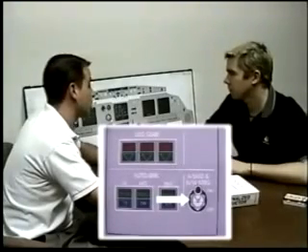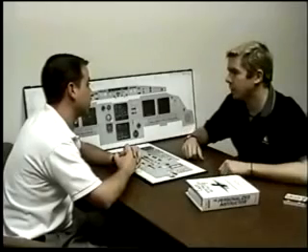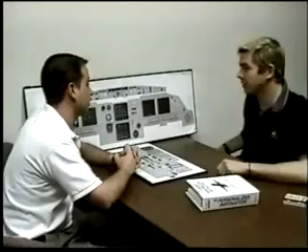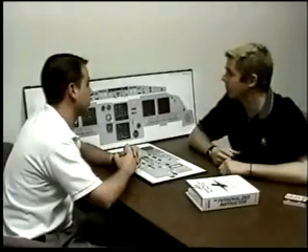What if the alternate brakes won't stop the aircraft? Well, if that doesn't, you're going to have to hope that the parking brake is going to work. So you reach down, turn the parking brake on, and that's going to stop you pretty abruptly.